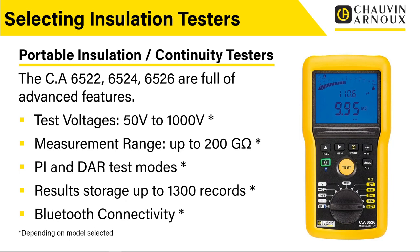So for example, we've got the PI test, the polarization index test, and the DAR test. That's included within these testers, particularly within the 6526 and I think the 6524 as well. So these are tests that would help you if you were testing a motor and looking at the quality of the insulation of a motor or transformer or something like that. These are features you'd expect to see probably on the more advanced, chunkier testers that we'll talk about in the next webinar, included in these products.